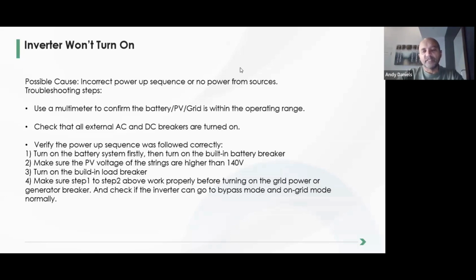But since then, we've changed our logic, so you can power it on with battery. And then once the battery's powering on correctly, PV's on correctly, and AC's on, then you can go into the setup and change the battery configuration. In other words, you confirm the battery manufacturer, for instance Lithium, and who the manufacturer is, and then you make sure that the battery communication is correct.